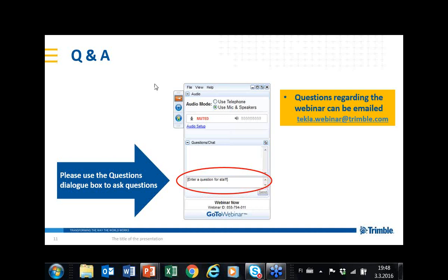Okay, thank you. And then there is another one, relating to the detailing manager. How many rules may I create for the detailing manager at one time? Well, basically you can add 15 tab pages, so the answer is 15 rules. But for advanced use, you could actually create a rule that inserts the detailing manager component. In that way, you can basically have more rules than you ever need.